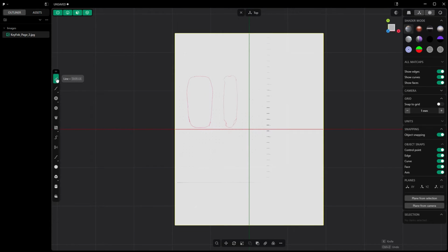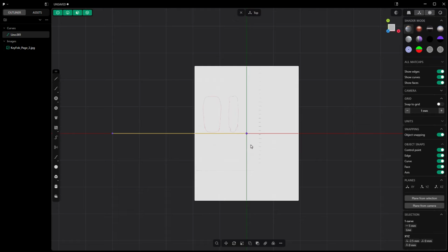And then I'm going to start a new line. The line tool from the origin, I'm going to drag out to the left and then hit my tab key. Because for me, the distance between the points on my reference paper is 5 millimeters, I'm going to create a 5 millimeter line and hit enter. This tells me that the image that I brought in is way too small. If you happen to create a mark on your paper that was 25 millimeters long, or if you have grid paper that's at 10 millimeters, then you would want to make sure your line is appropriately sized.